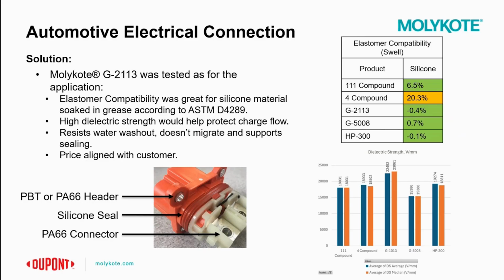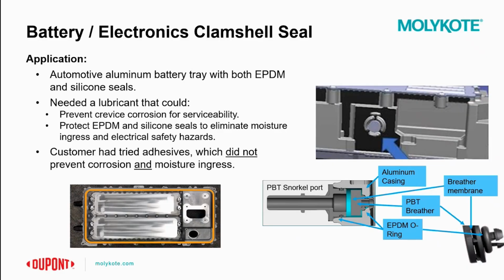When testing compatibility with the materials making up this connection, G2113 showed great performance on par with HP300, which is a fully fluorinated product known to be the pinnacle of compatibility. Along with that, G2113 showed great dielectric strength, which would help insulate and protect the connection's charge flow. And lastly, G2113 is great at resisting water washout to help support the function of the pass-through seal. Moving to our second case study, here we have an electronics clamshell seal.